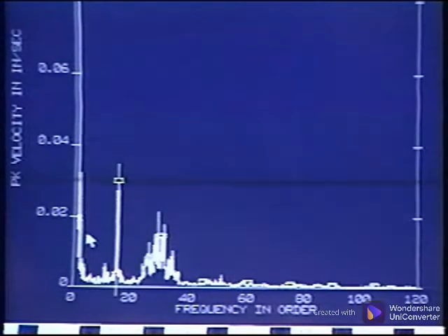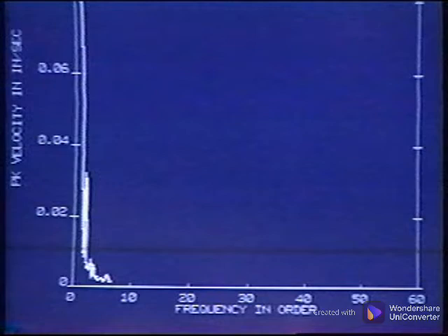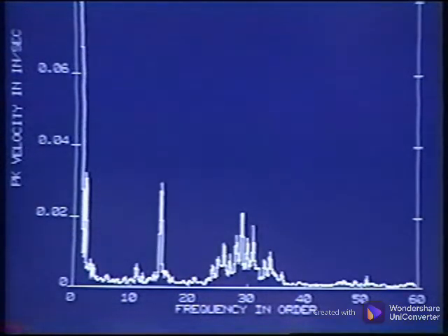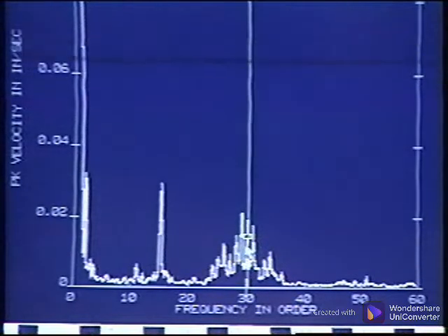This spectrum from the input shaft is similar to the data shown for the excessive gear wear. The gear mesh frequency is at 15 times turning speed. Notice how the second harmonic of gear mesh frequency has much more energy around it. When the area around 2 times gear mesh is expanded, we can see the detail better. Locating the peak at 30 orders or 2 times gear mesh, we see that it is smaller than the peaks around it. Marking this peak, we move over to another peak to determine the spacing.